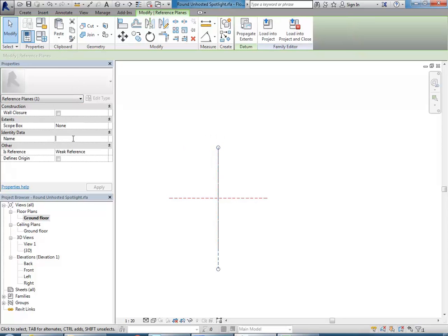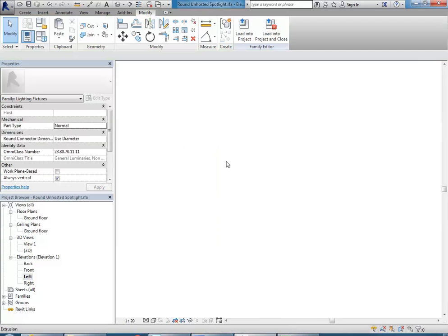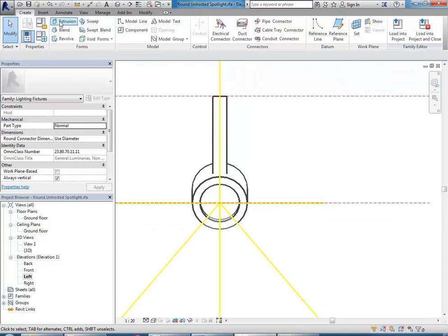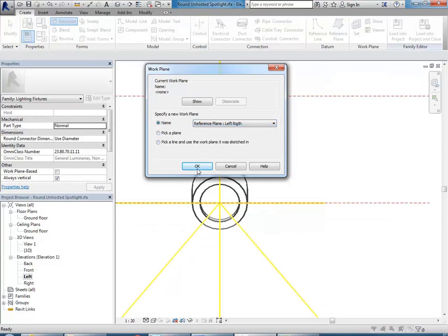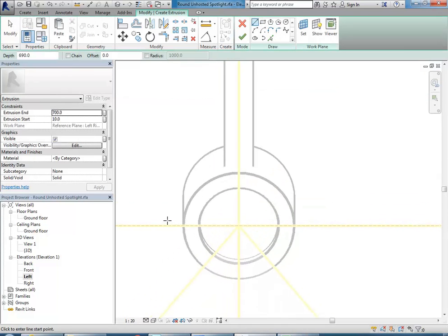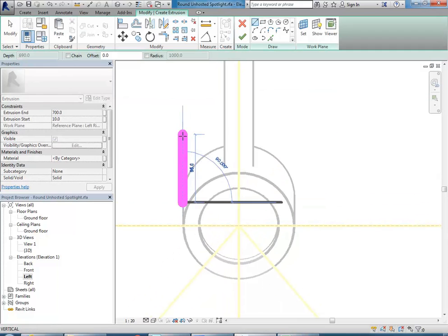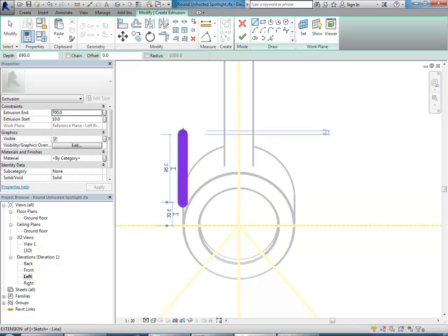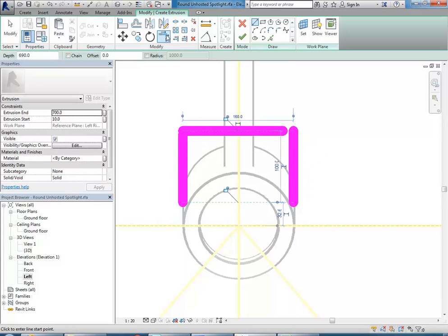There we go. Okay, so left, right is what I'm going to call this plane. Just to prove to you it will be 30 seconds, but just after getting that plane in. Okay, so now back to extrusion, and I can choose left, right, and simply draw a housing. So a bracket essentially. It's like a hinge, for the hinge to rotate within, so it doesn't look strange.